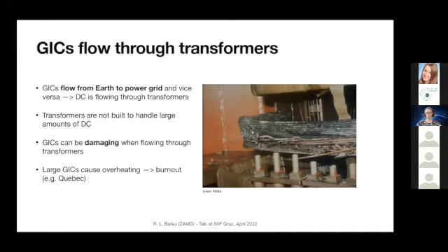So when you get DC in transformers, they can cause a variety of problems, the worst being overheating. In the mild case, you can just get some mild operation problems in the transformers and in the power grid. But if you get prolonged large DC, you get an overheating of the transformer and eventual burnout or explosion if it's really bad. The picture on the right shows the transformer windings after a fire. That is the one in Quebec. That is what led to that power outage that I showed in the beginning.